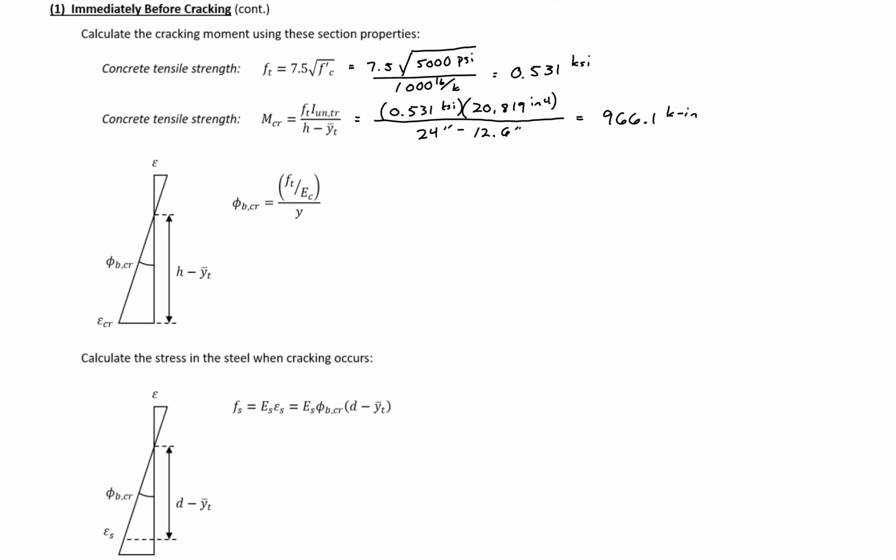Note that this distance on the bottom is the distance from our centroid to our extreme tension fiber, where cracking will first occur.